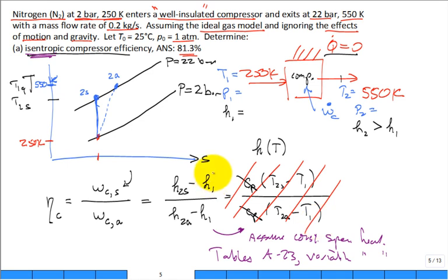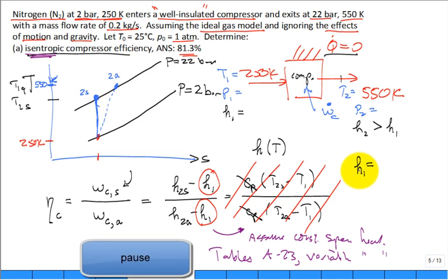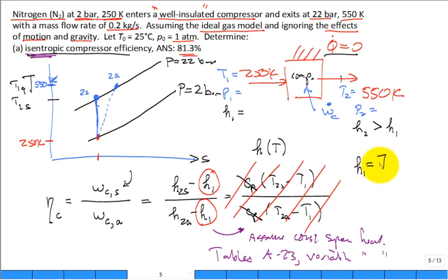Can you go into the table and get H1? We need that in this equation. What is H1 equal to in the table? 7266. And we're good engineers, so we're going to put our units down. What are the units on that H? Kilojoules per kilomole. And if I look at this equation, I have one little typo or syntax error. What's my error that I need to fix? It's on a per unit mole basis.